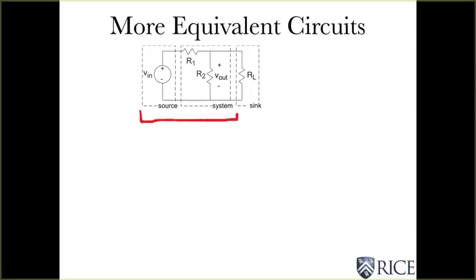Well, if you're going to actually use that voltage for something, it has to be attached to the sink. Remember our old system thinking that we have to send our message to the sink. And the input to most circuits that we care about looks like a simple resistor. And so the question is, if I attach my circuit to the receiving circuit, which is going to look like a resistor, does that change the output voltage V out?